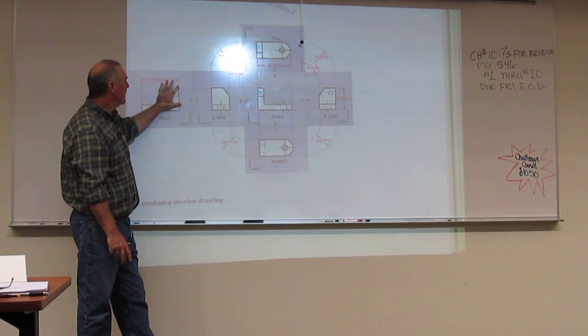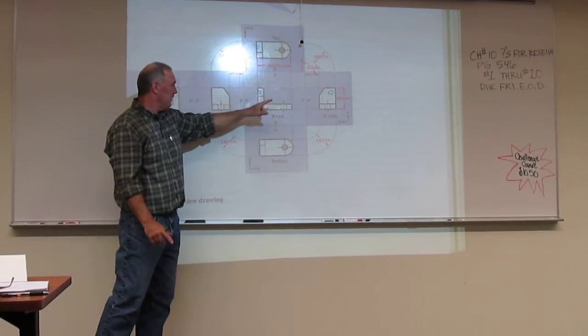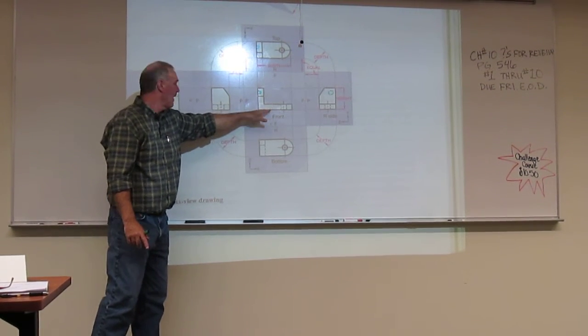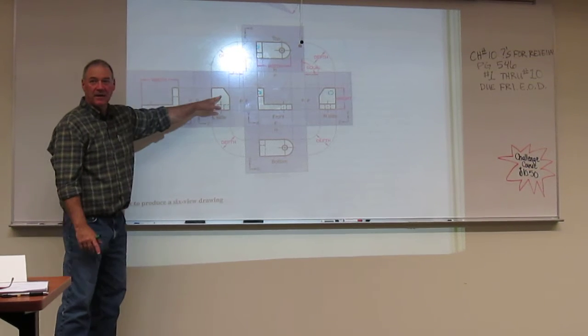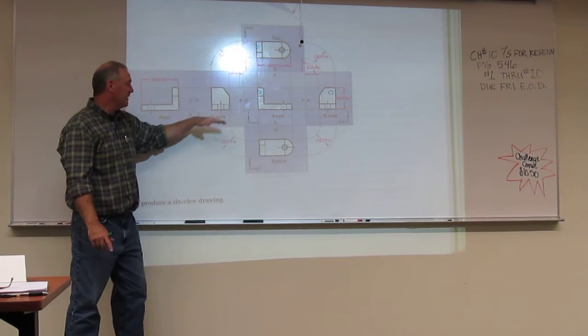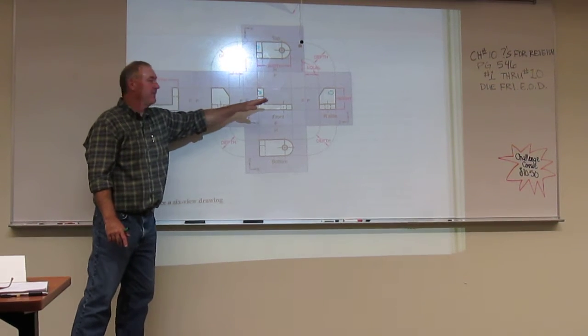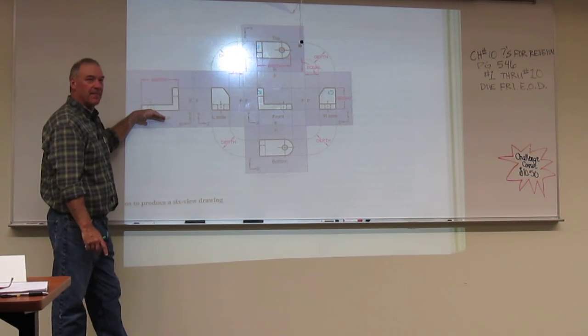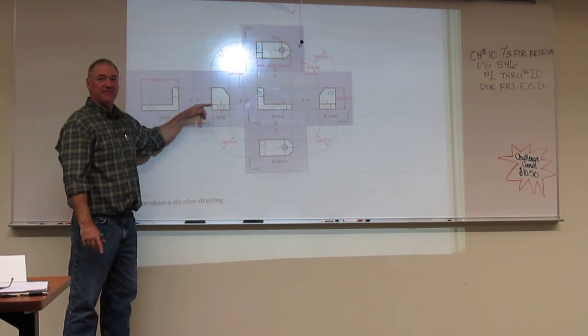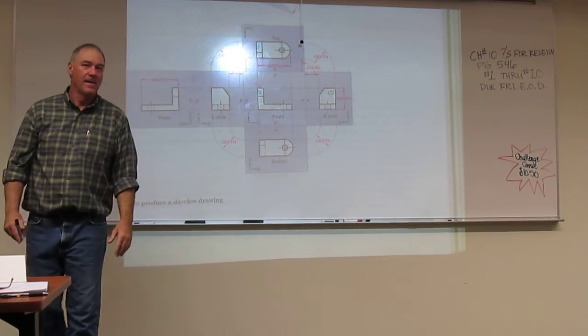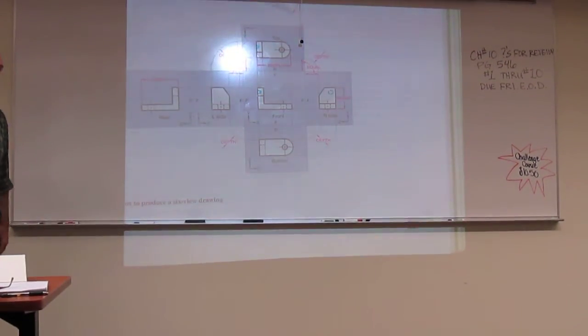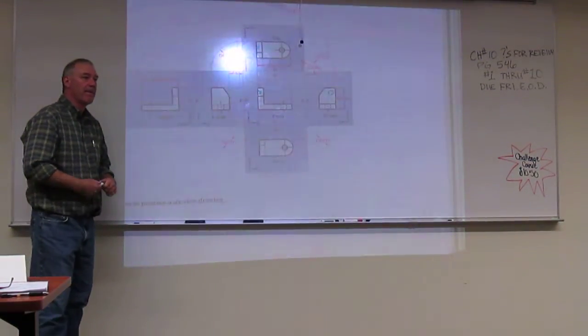Now, what you can't do is a front view and then throw in a rear view without a left. Because then somebody's going to get confused and say, no, this is supposed to be a left. So they want to see a front, then a left, and a rear. Even if this one doesn't give any new stuff, I'm still going to do it. So you wouldn't drop the front? No, every object has a front. I could drop the right if I had to.